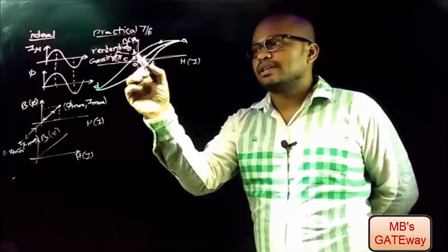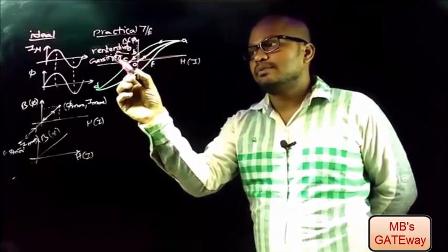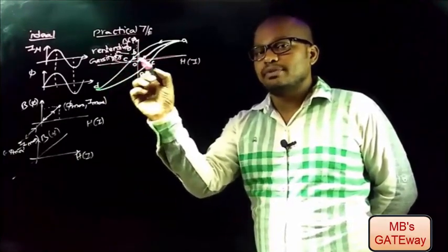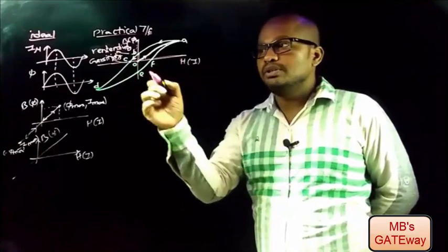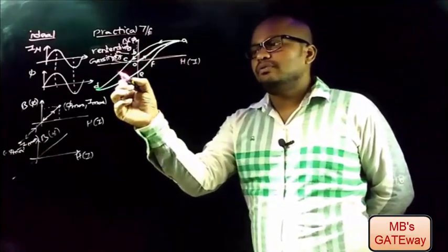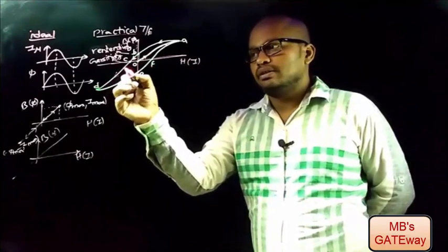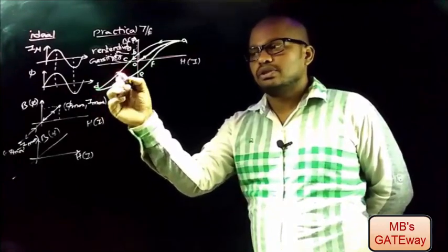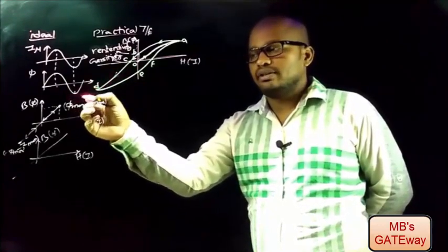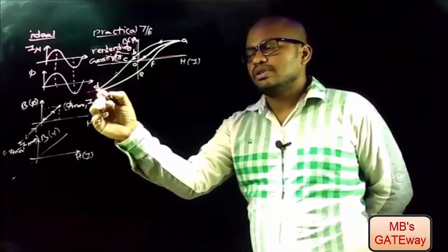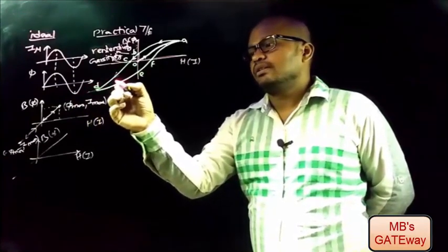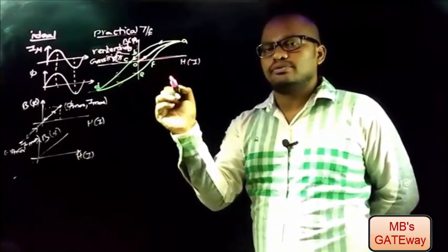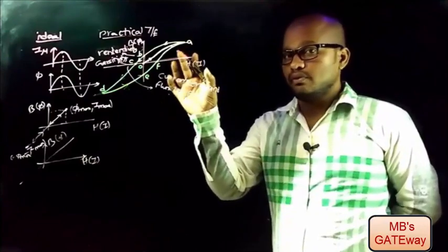And now if you observe, the curve has reached C, and this point C represents the coercivity. This represents the amount of reversal magnetism that is to be applied to the magnetic core to bring the residual flux to zero. And now with further decrease in current I, the curve will follow like this, and in the reverse direction the magnetic core will attain saturation, so there will be no further decrease in the flux phi, and the curve will be constant. And now with increase in current I, the curve path will be like this and reaches point E and then point F. Here our focus is not on the discussion of the BH curve.